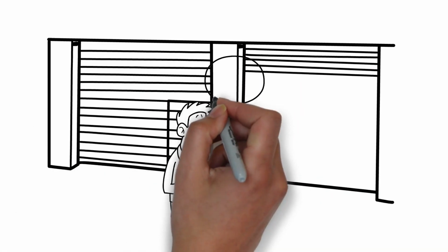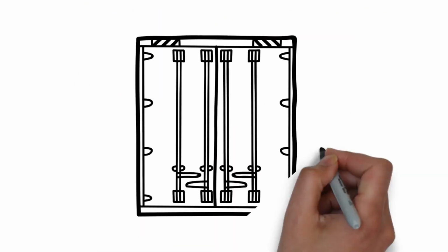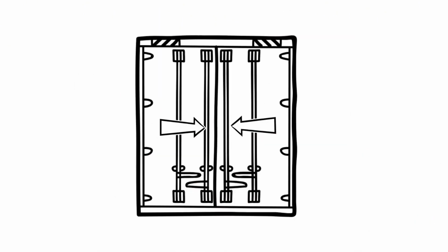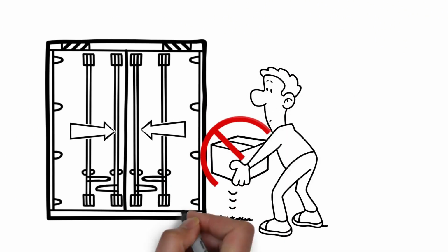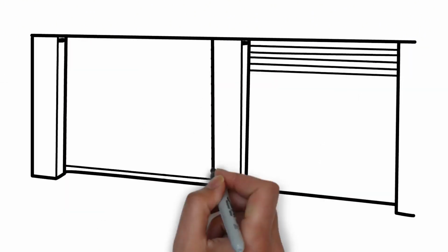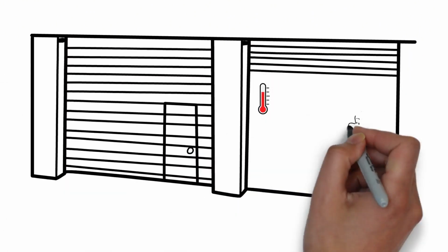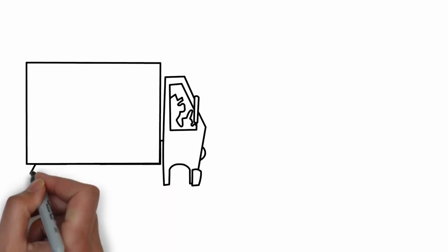Handle temperature deviations immediately. If the dock temperature goes above 40 degrees Fahrenheit, close the container doors between movements and store the product in its designated temperature zone. Suspend loading temporarily until conditions are corrected. No staging on non-refrigerated docks. This rule is non-negotiable for temperature-controlled products.